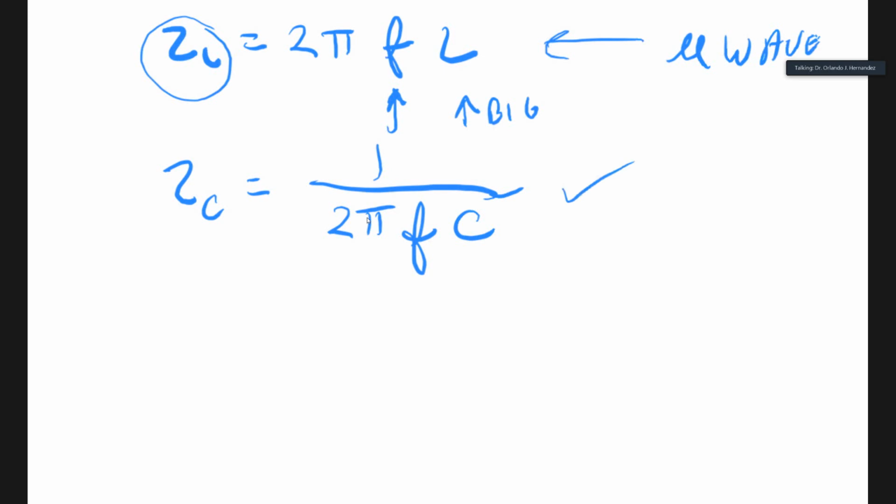And we want amplifiers, so we can make amplifiers with MOSFETs. So we'll see that later on, because MOSFETs is pretty much all we have. And then we can also make capacitors, fairly good capacitors with integrated circuit technology, and even by using MOSFETs, because the MOSFET is really a capacitor.